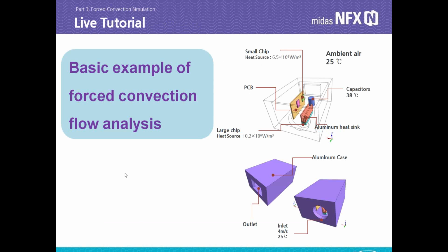So now we will begin the big part of today's webinar, which is the forced convection flow analysis in Midas NFX. So I will show you the full process, how to perform such analysis. So here you have a view of the system that I will consider. You have a small PCB with 2 chips. You have a larger chip with a heat sink in aluminium, and you have a capacitor which is also in aluminium. So the ambient air is at 25 degrees Celsius.